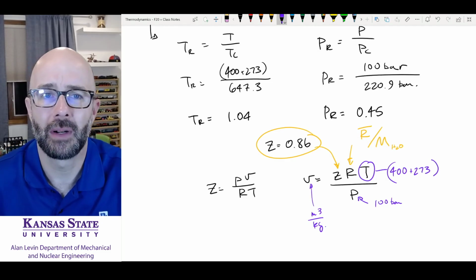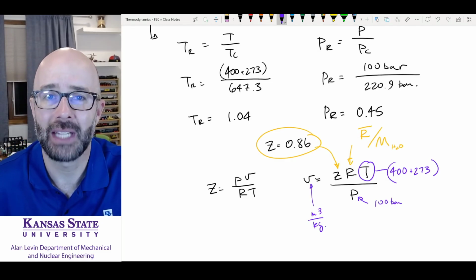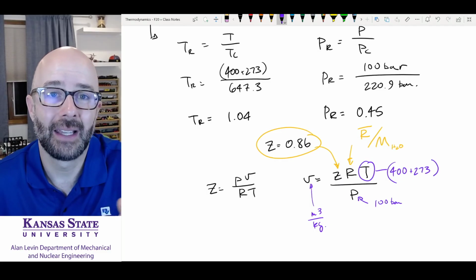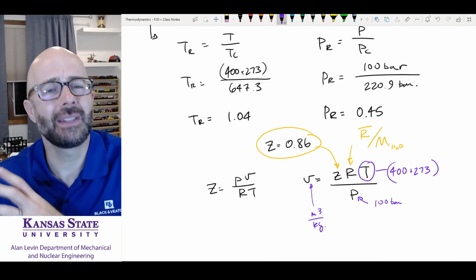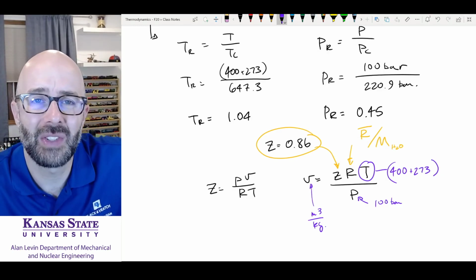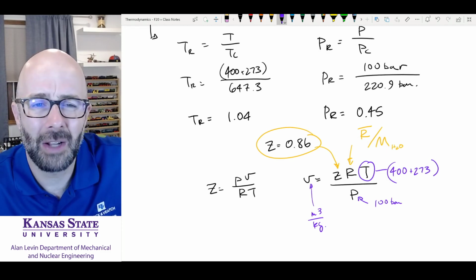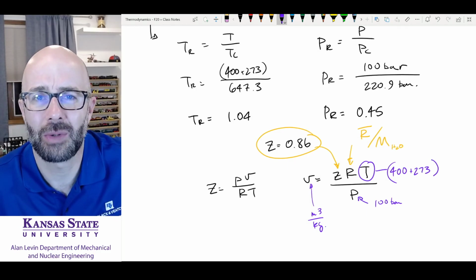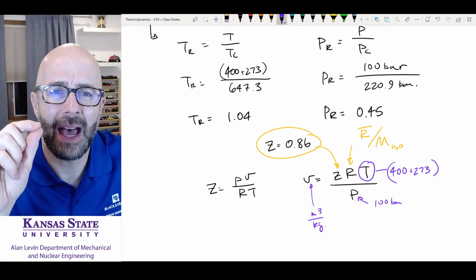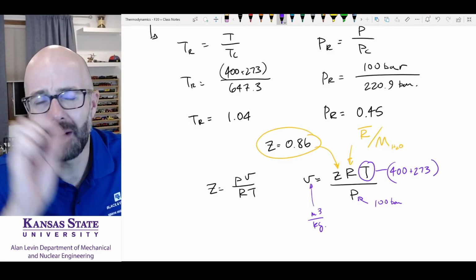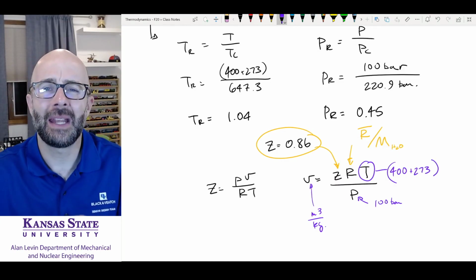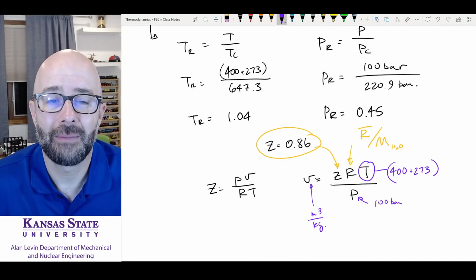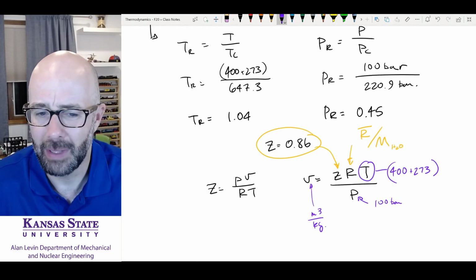Every time we dealt with water vapor, R22, R134A, propane, and ammonia in a vapor state, we were dealing with them as a real gas. Here, when Z is not equal to 1, we're considering a real gas. But starting next week, we're going to say that most of the time the Z values for this set of gases are going to be so dang close to 1 that it would simplify our life just to assume ideal gas. Yes, our calculations are going to be a tad off from the actuality, but in accepting that small difference, we can eliminate a huge amount of calculations, which you can mess up anyway. So that ideal gas assumption is a very powerful assumption that we'll be taking advantage of.